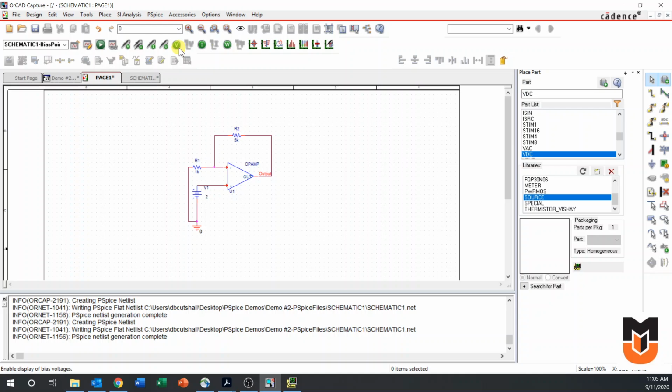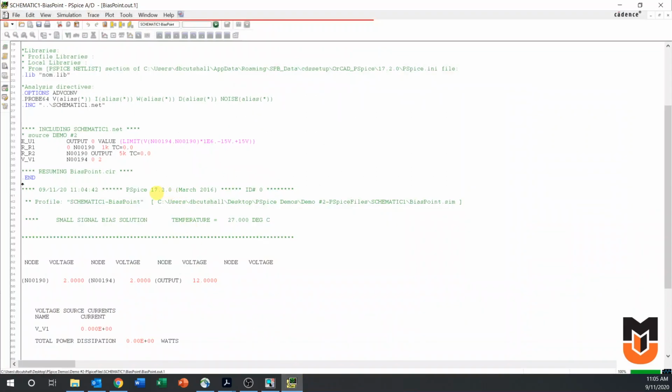Similarly, we can click on this V. This is something where PSpice sometimes gets a little annoying, in my opinion, because notice that these voltages haven't updated from when we ran our previous simulation. So be cautious trusting these values. If you're ever uncertain, a good way to get around that is to just restart PSpice entirely. But whenever possible, it's usually better to rely on these output files, whether it's the simulation results or the plotting data here.